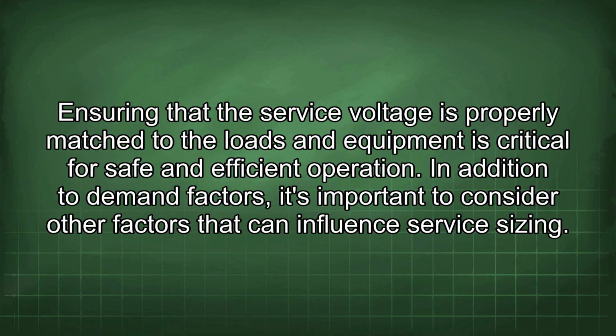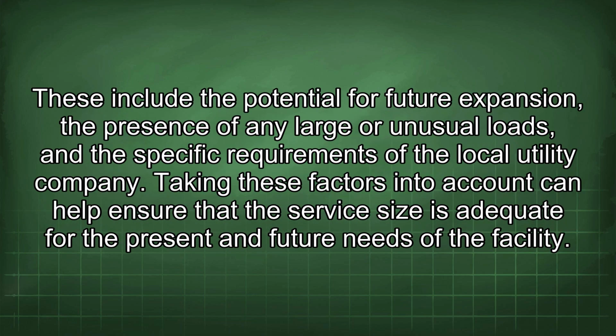In addition to demand factors, it's important to consider other factors that can influence service sizing. These include the potential for future expansion, the presence of any large or unusual loads, and the specific requirements of the local utility company. Taking these factors into account can help ensure that the service size is adequate for the present and future needs of the facility.